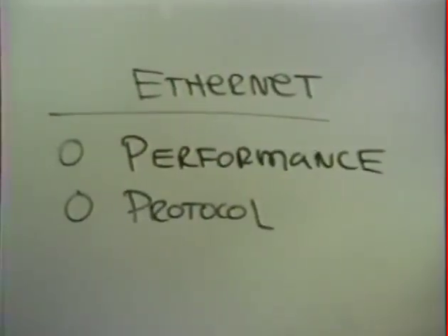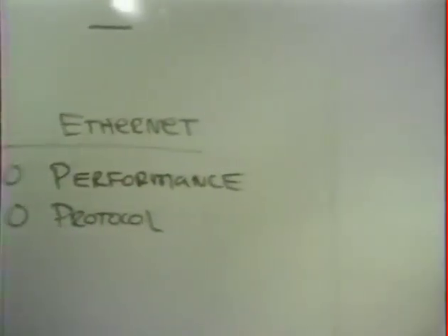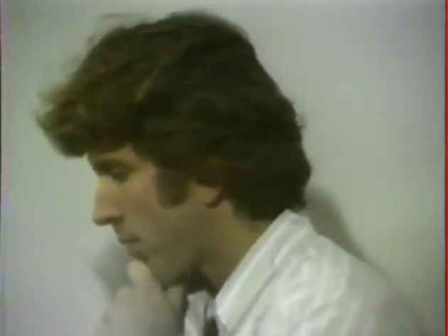In this talk now, I think I've finished describing the performance of the Ethernet, in particular trying to contrast it to the Aloha network, and showed that we could get asymptotically close to 100% utilization of the coax through this distributed algorithm, distributed packet switching that we have, which relies on carrier detection and interference detection.